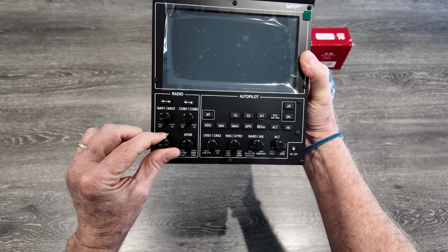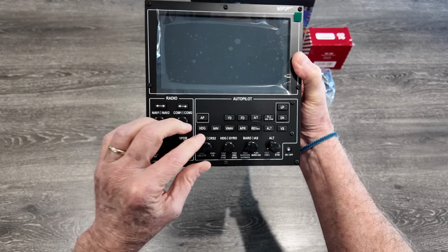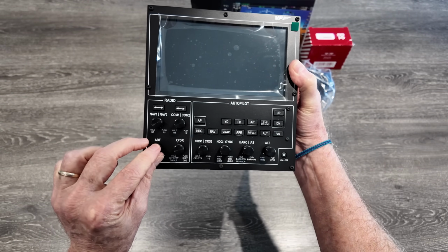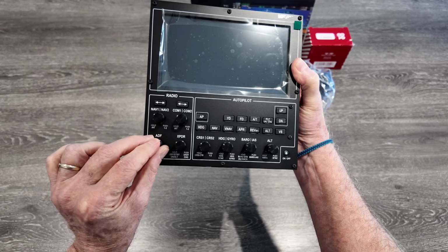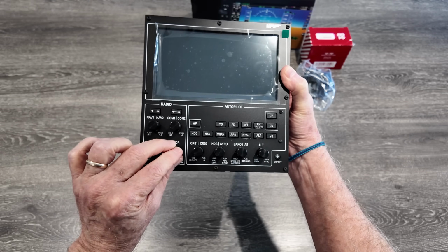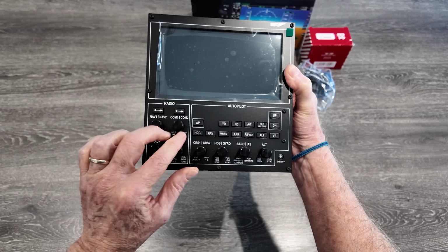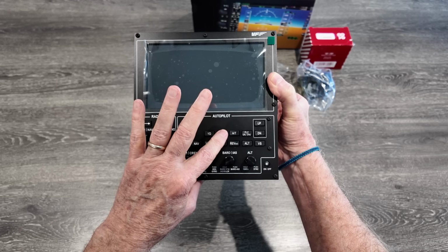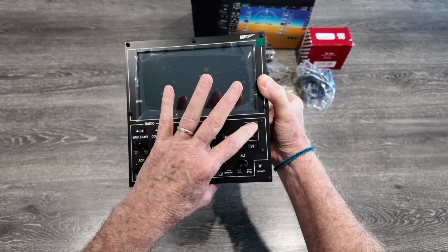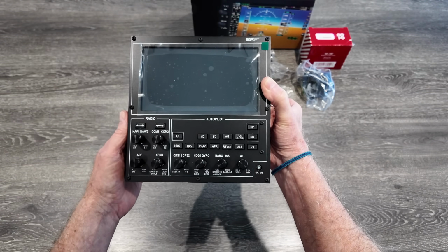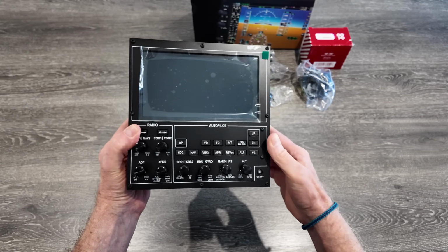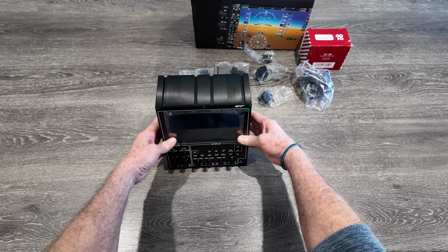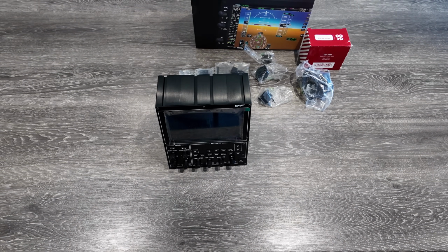What the unit doesn't have are the dual rotaries that perhaps we're used to, although they do have a dual rotary function. Typically for nav1, for example, press the rotary in, it acts as a button, and it switches between nav1 and nav2. Rotate the dial and it changes the decimal numbers. Push down and rotate and it changes the whole numbers. Personally, I'd have preferred dual rotaries, but it's fairly intuitive and quick and easy to use, as I'll be demonstrating shortly. Some of the rotaries have up to 3 functions.